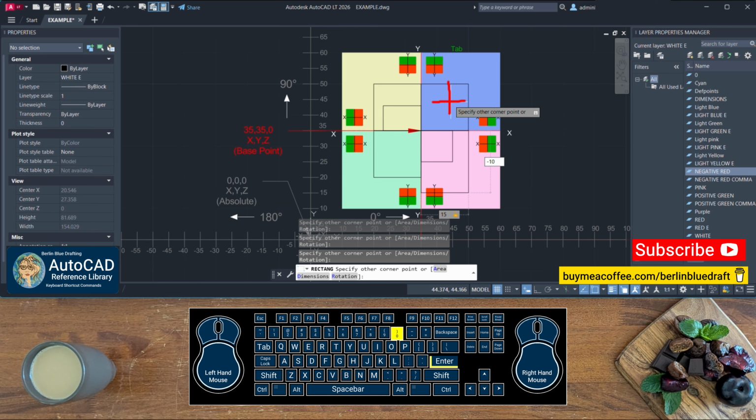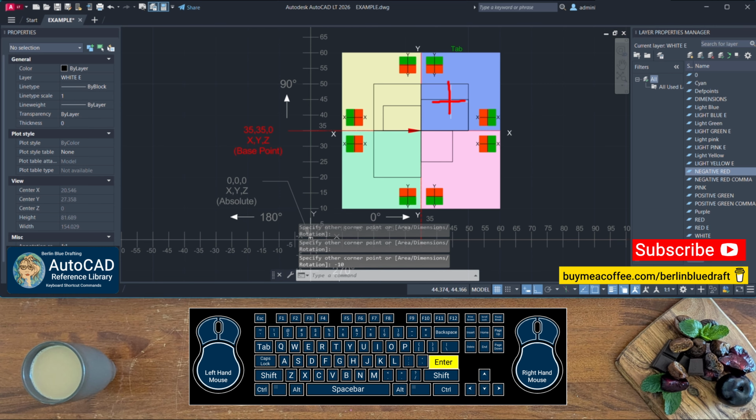The positive and negative X and Y values are always referenced from the crosshairs, the second corner point. Regardless of whether you input negative or positive values, once the shape is created in the new quadrant, the values will be displayed as positive. This demonstration should help clarify how to use the rectangle tool with the Tab key to separate X and Y, and how the matrix of the coloured fields determines the placement and orientation of the rectangle or square. For more information on using the comma to separate values, refer to my next video on this subject.